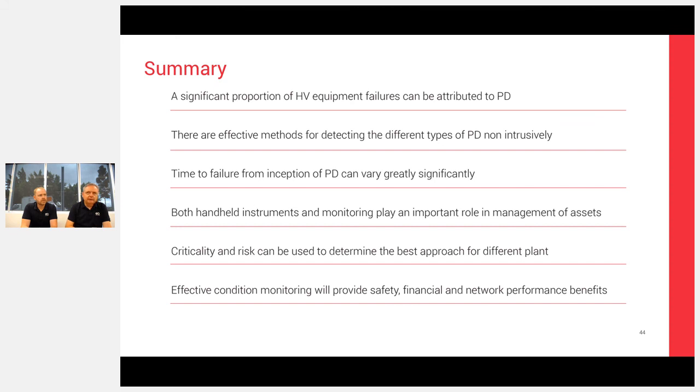So when you're finding TEV activity and you open something up, you often don't see anything because it's on the inside of the installation. You'll open up a CT chamber, for example, on Reyrolle LMT, and it will look absolutely perfect, but inside it's discharging. So sometimes you can't see it. The compound insulated cable box that Brad showed in the case study would be very difficult to actually find a problem in. By the time you melted the compound out, it may have gone, although it can be found. So sometimes it's difficult to find something.